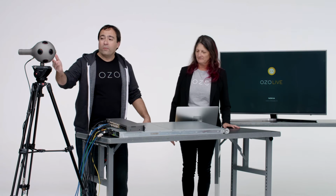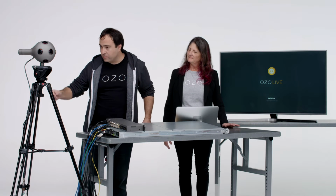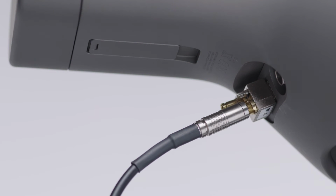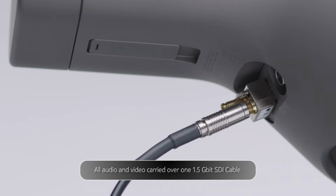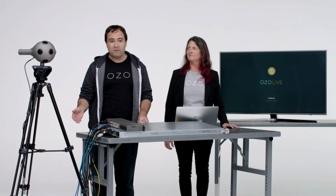You start with the OZO camera, which captures video and audio in 360 degrees, 3D stereoscopic. The signal that comes out of the OZO is a single HD SDI cable. This carries all of the data from the cameras, sensors, and the microphones in a compressed proprietary format that's packed into standard HD SDI protocols. What this means is that you can treat this cable more or less like any other video cable. You can run it through hubs, you can run it through recorders, and you can switch it to fiber even, and run it on fiber across the country if you like.